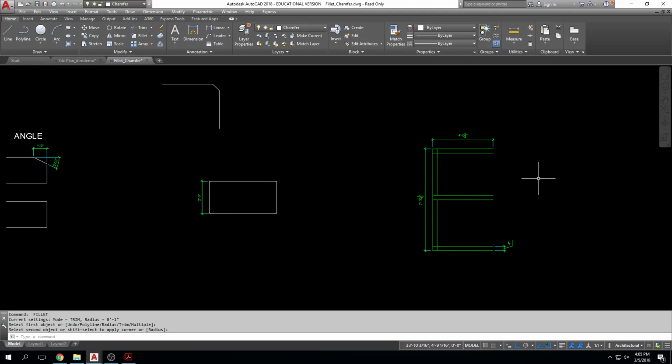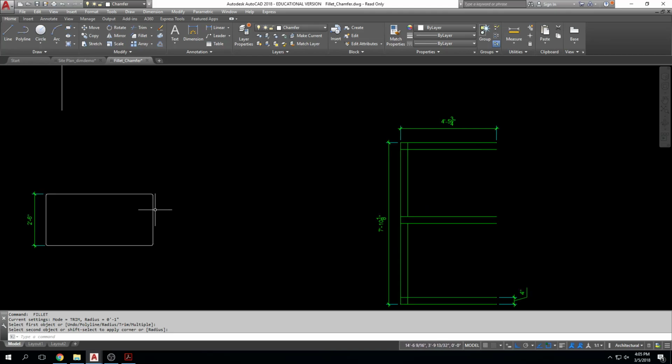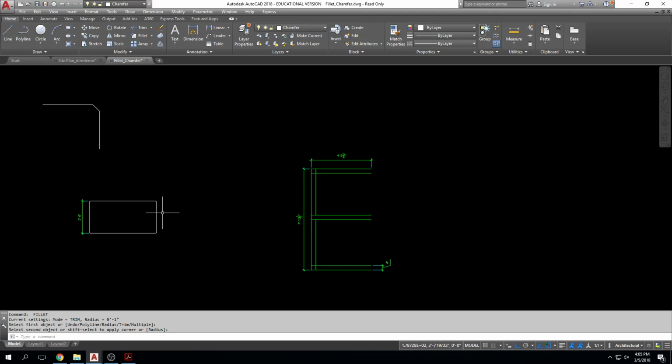One trick, not tricky thing, but one kind of trick of fillet is not only will it round corners, right? Especially for civil engineers, you're drawing curb cuts or site plans that need something with a specific radius, because, I'm making it up, but a right-of-way has to have a 13 or 12 foot radius, right? This would be really helpful because you can take 2 lines, you can join them together, and you can fillet them with a radius that's appropriate for whatever you're drawing, okay?